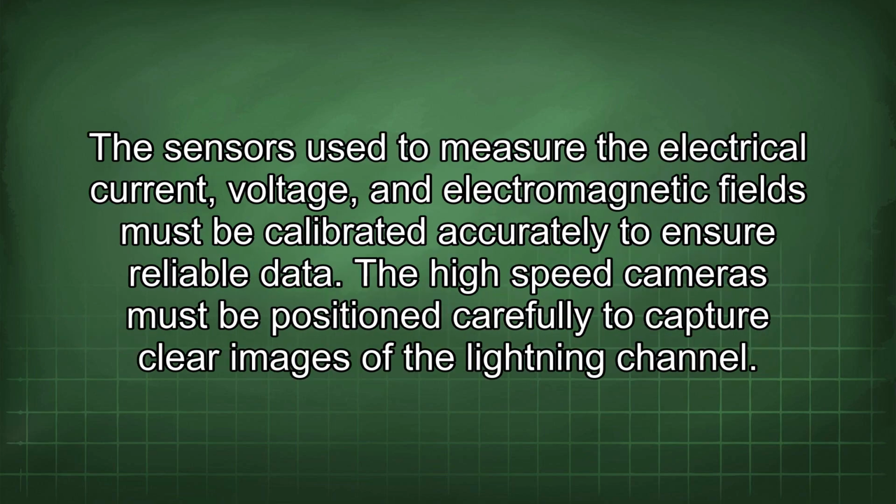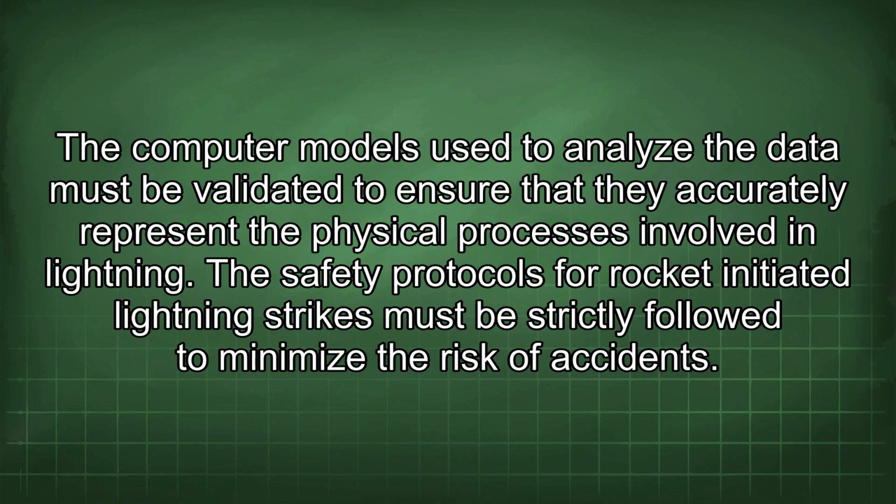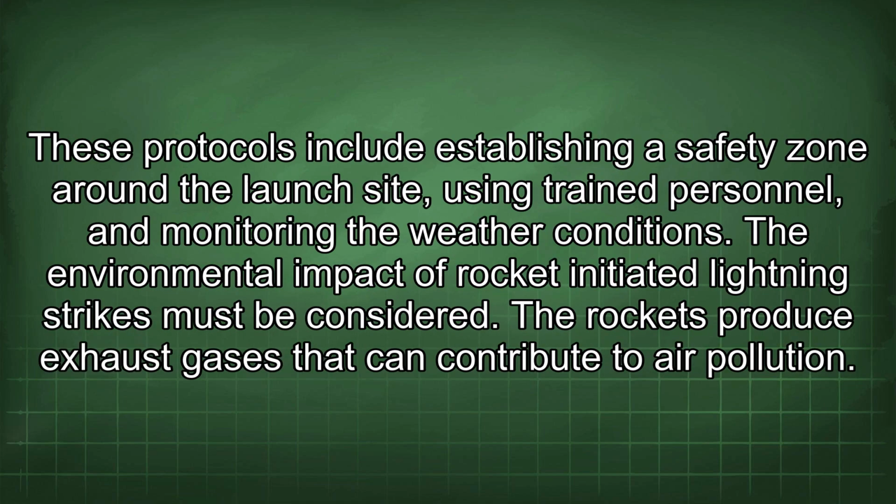The sensors used to measure the electrical current, voltage, and electromagnetic fields must be calibrated accurately to ensure reliable data. The high-speed cameras must be positioned carefully to capture clear images of the lightning channel. The computer models used to analyze the data must be validated to ensure that they accurately represent the physical processes involved in lightning. The safety protocols for rocket-initiated lightning strikes must be strictly followed to minimize the risk of accidents. These protocols include establishing a safety zone around the launch site, using trained personnel, and monitoring the weather conditions.